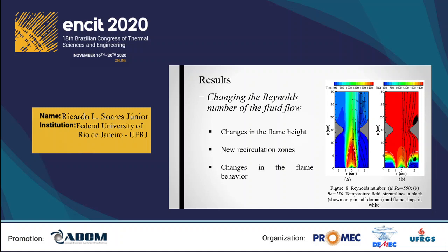This large amount of oxidant also changes the convection intensity, modifying the position of the recirculation zone downstream of the irregularity position, which is formed at a higher axial position. The area of the recirculation zone is also modified, caused by the fluid flow separation induced by the regular wall shape itself. The recirculation zone becomes much less intense with a bigger area, extrapolating the solution domain.